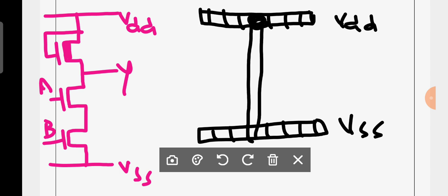and there may be definitely a contact. Why? Because two different layers interact with each other, a contact will form. And you require depletion mode transistor, as it is same in this manner itself. I am considering a depletion mode transistor. Don't forget, this is what? Polysilicon. And you require an implant here.